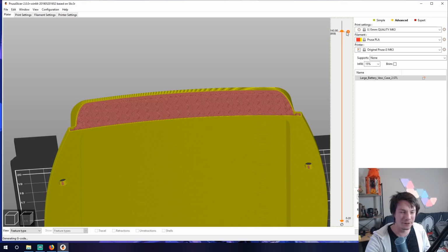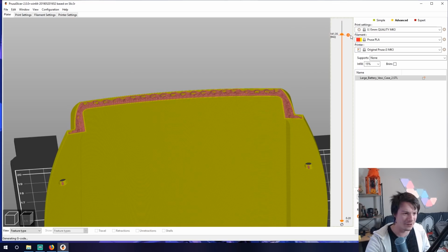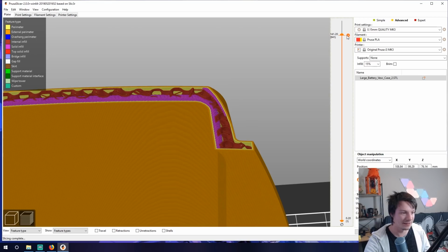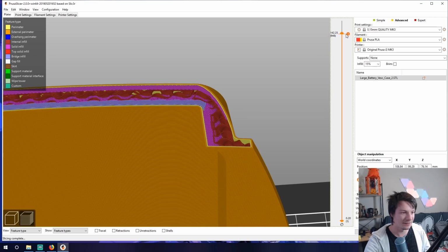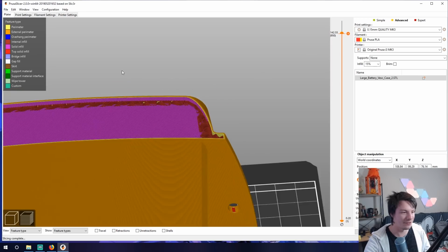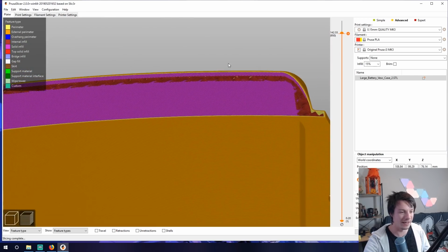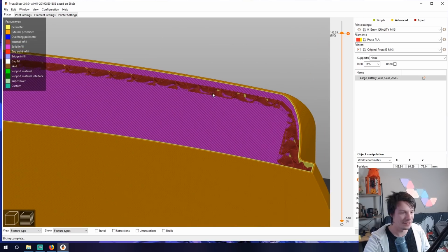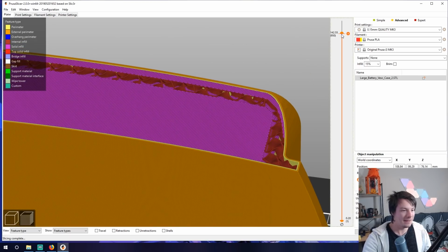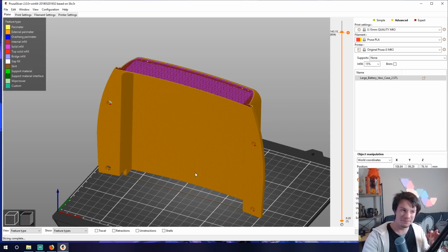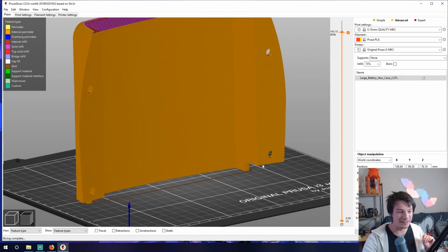See that gyroid infill? Not necessary for this at all. So you can see here, as it starts to go up, it goes more and more over thin air. Like that. Okay, then we do have a very substantial bridge. That's one layer going across. I think we could get away with it, but it's pretty close. It's not going to look very pretty, but we can get away with it. We can't get away with the overhang down at the bottom.